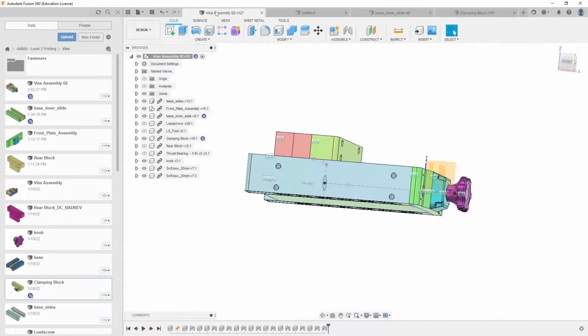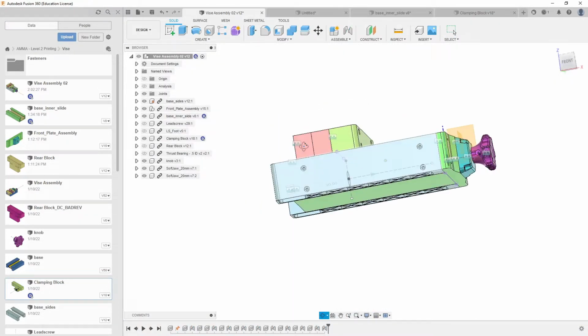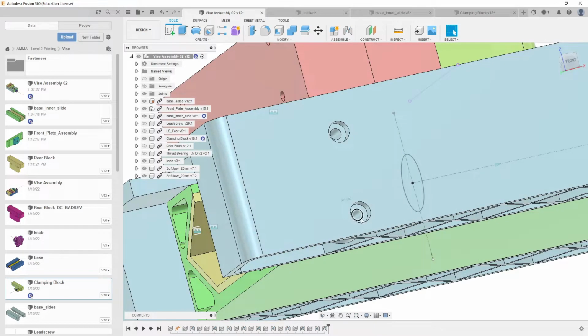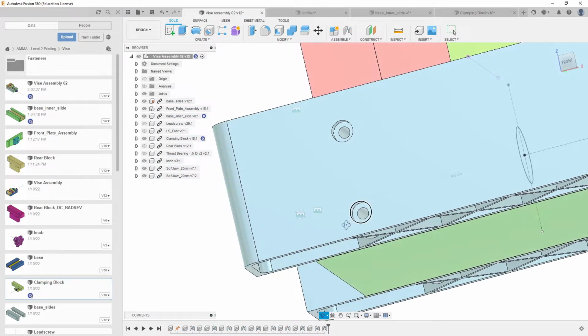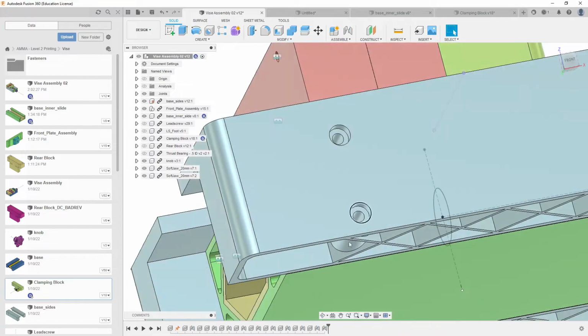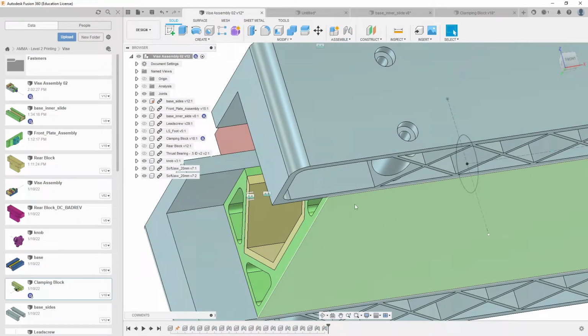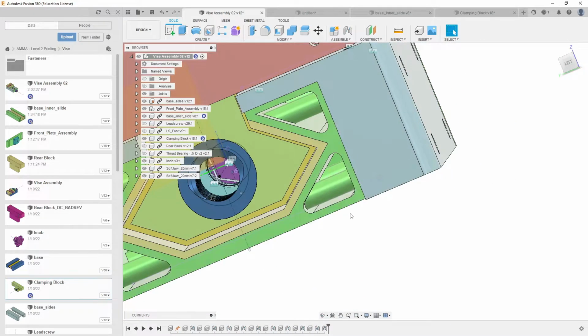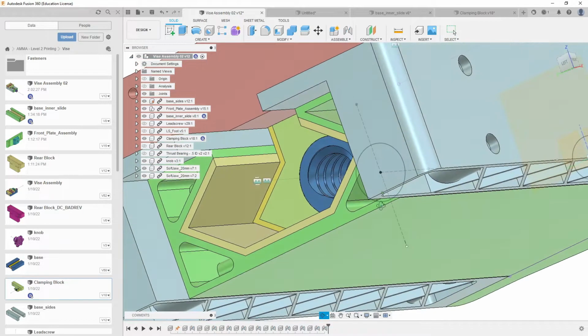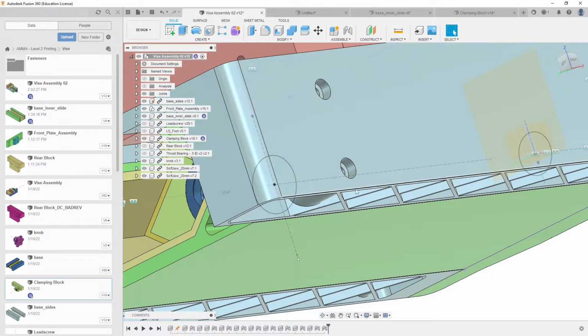But if we go over here, this does. And you could say that that doesn't really matter because it's not the part. But if our hole is too low down here, because it seems like the edge margin is okay for just a 3mm hole, if we don't account for the counter bore, this part is going to be coming out at the bottom of the part.